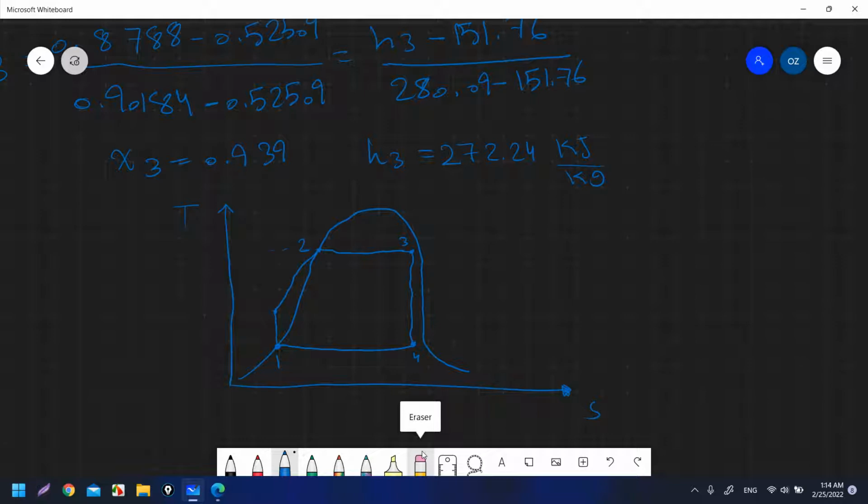It is equal to these temperatures. They are at the same line. Okay, so they have the same temperature. So we can say that T2 also in this question is equal to T3, and this temperature is the saturation temperature. Okay, because it is inside the dome, it is a constant line, so it is equal to the saturation temperature because it is in the saturation region in the mixture. Okay, so it is equal to Tsat.